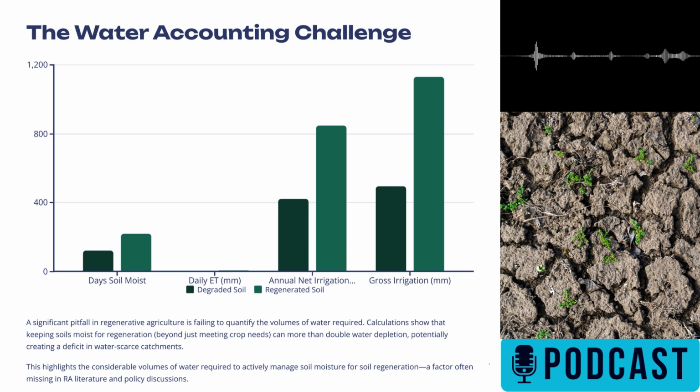And what's really insightful, I think, is that RAM is a strong indicator of the physical health of the soil under RA. How so? Well, a soil that's recovering, getting better structure, will tend to hold a higher proportion of its total water, its TAM, in that readily available range. Maybe 40 to 70% of TAM could be RAM. Which is good for the plants. Ideal, yeah. And it gives you more flexibility if you're irrigating. A low RAM, say less than 40% of TAM, suggests the soil structure is poor, degraded.